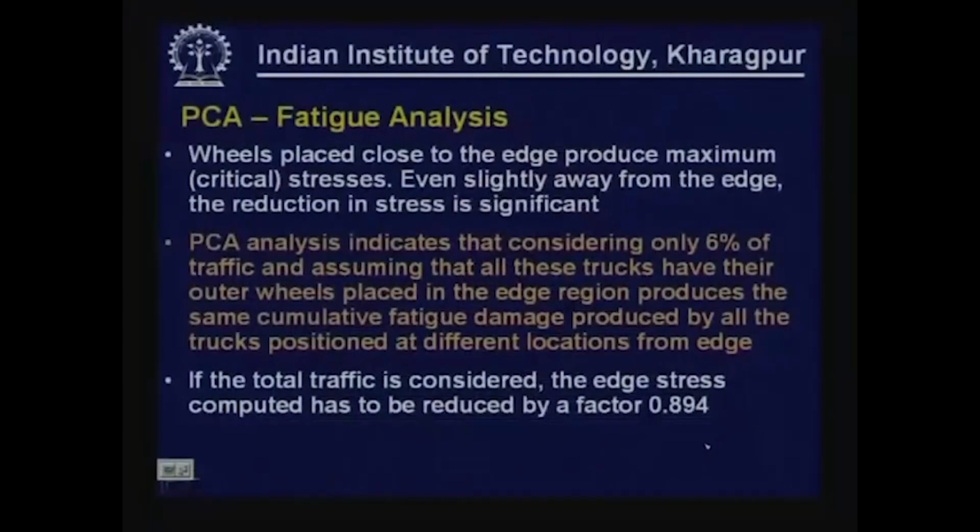If the total traffic is considered, for example, if you assume all the 100% repetitions, then it can still be done, but the edge stress computed will have to be reduced by a factor of 0.894. That will correspond to the actual total cumulative damage that you can obtain.